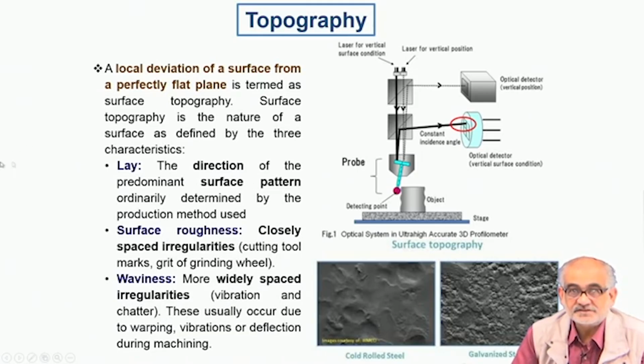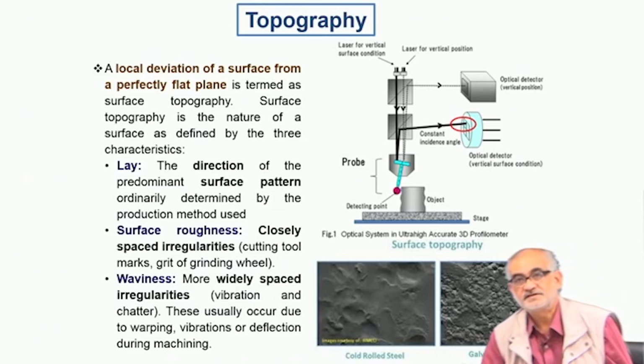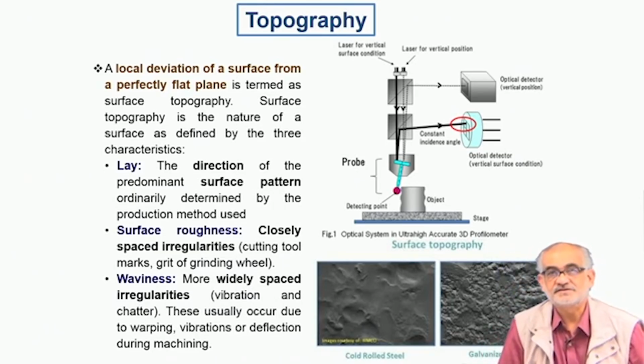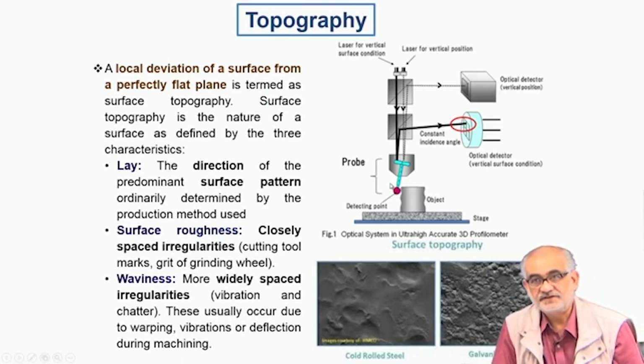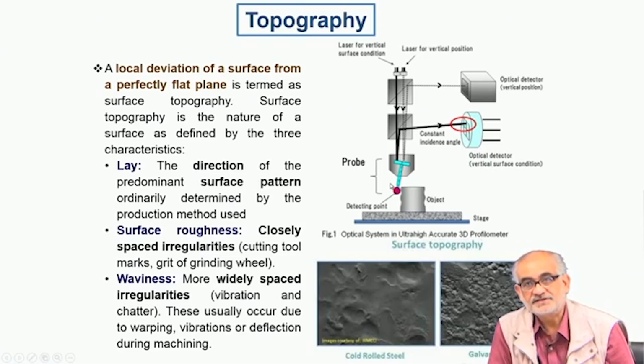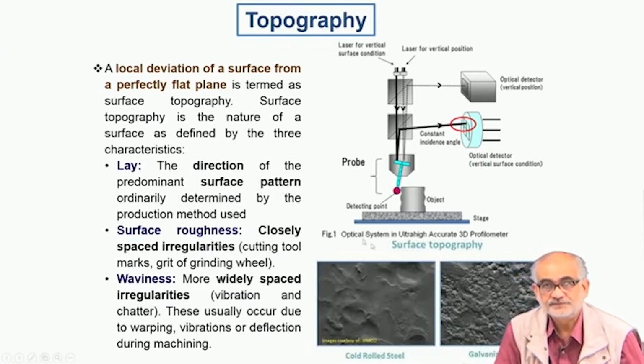So whenever we have such topological or topographical variations and we need to measure them, then we employ one of these profilometers, which could be a contact type like here, or a non-contact profilometer. In a non-contact profilometer, we generally follow the reflection profile, and the surface, if it has certain levels of waviness or roughness, will definitely show different kinds of contour.